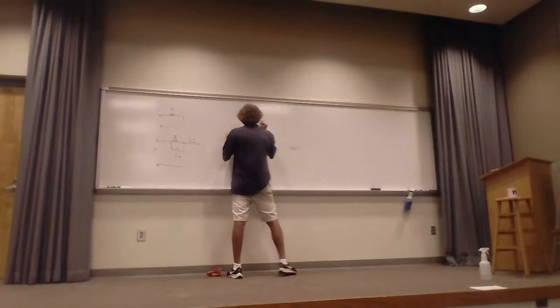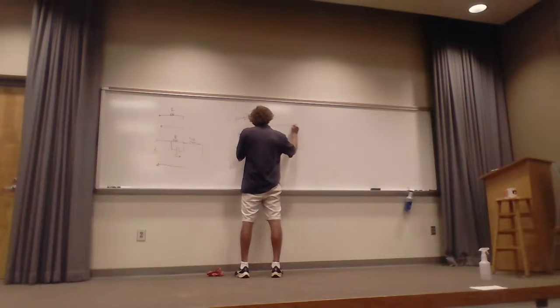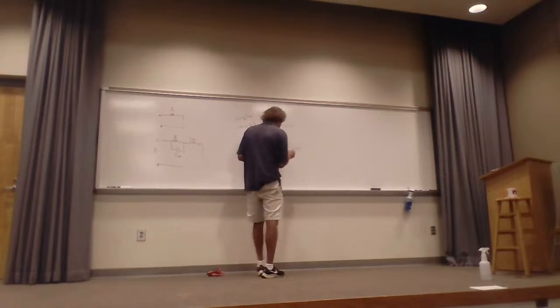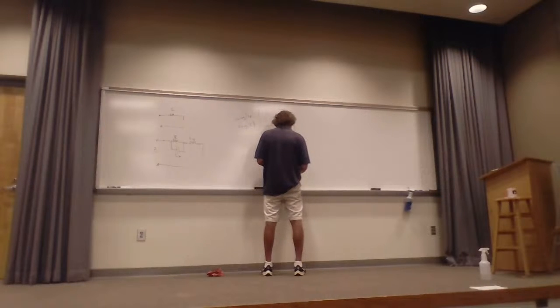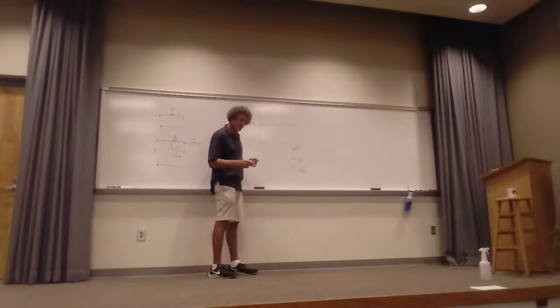And if we take the log of S here versus 20 times the log of the actual impedance of that resistor, what we'll get is this. It'll be a constant value, and this will be just 20 times the log of R, whatever the actual resistance is. Then there'll be a point right here, and that will be where really F is equal to 1 over 2 pi RC, or omega, since we're plotting omega, is really 1 over RC. That's the first cut frequency. It's the low frequency.